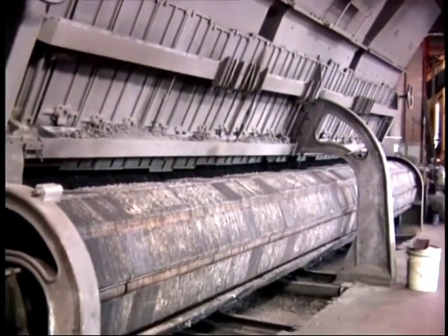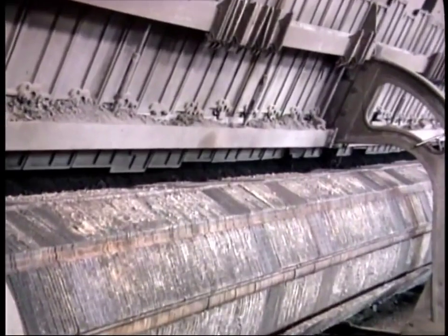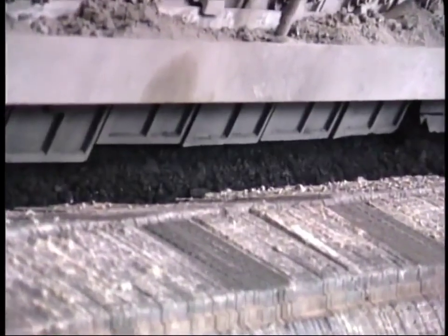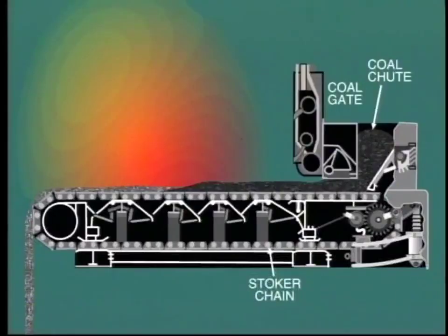Another common method of burning coal on smaller boilers is by use of a traveling grate. In this arrangement, coal is fed from the chute onto a grate, which then carries the coal bed into the furnace. The grate is really a continuous conveyor made of very rugged material to resist heat, erosion, and corrosion. Initially, the bed of coal does not ignite as its temperature is too low for ignition. However, after a few seconds, as the bed continuously moves forward, its temperature rises due to radiant heat transfer from the existing flame and refractory arch, and ignition takes place.